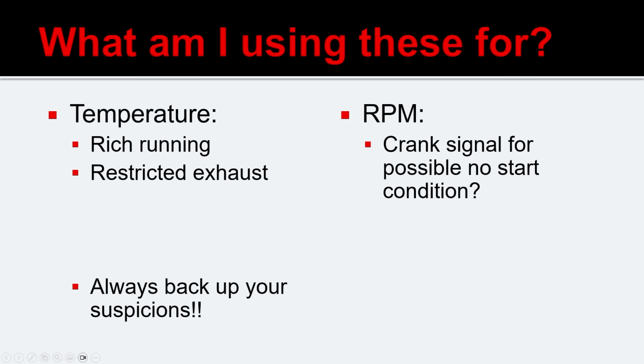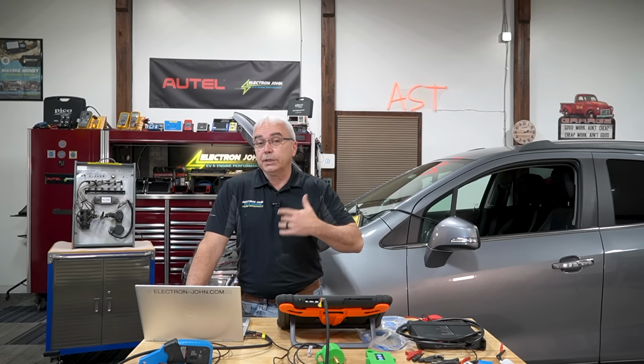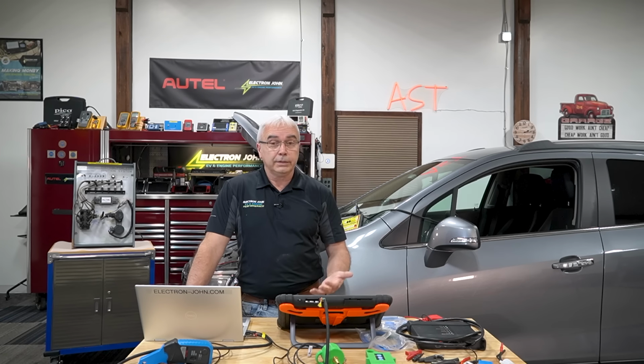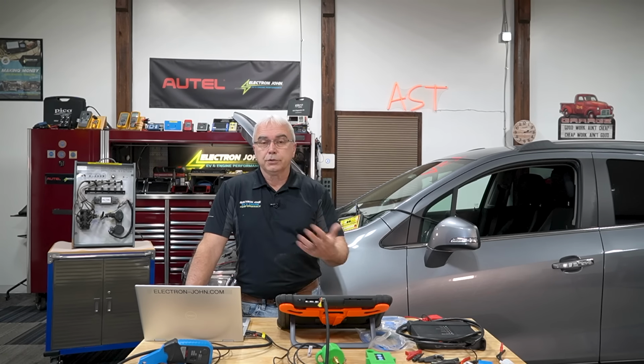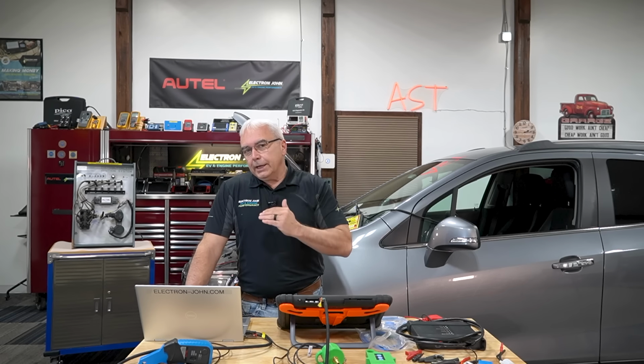So maybe the complaint comes in and it smells like rotten eggs or something because it's running rich, or maybe the fuel trim is telling me that it's trying to take away fuel for whatever reason. I'm also looking at my temperature PID for restricted exhaust, so an engine breathing type of ability. If I'm looking at my intake air temperature sensor, for instance, and I'm comparing that to similar inputs, like coolant temperature, maybe barometric pressure, stuff along those lines,